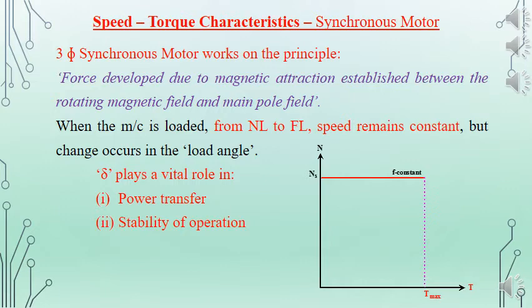And the thing that you will have to keep in mind, or the speciality or the change that happens in the case of synchronous motor, is in load angle. When the machine is loaded, the load angle will go on increasing, and there is a limit for the load angle. If the machine is loaded beyond a particular limit, or beyond full load capacity, the load angle will be above a critical limit and the machine will no more be running, or it will come to a standstill condition.